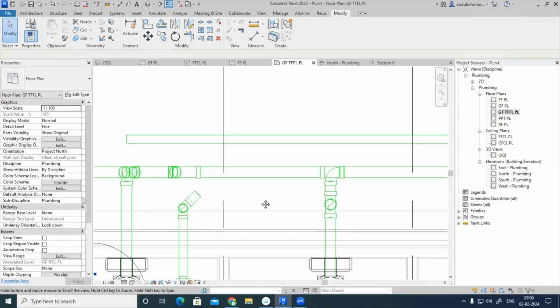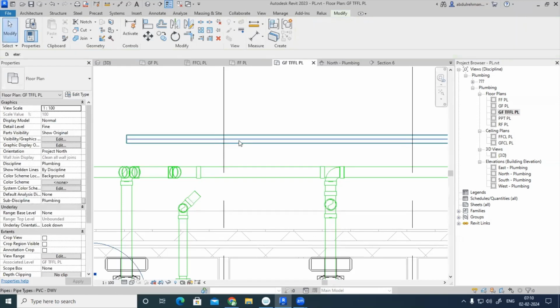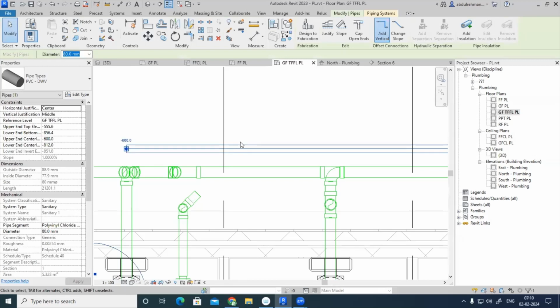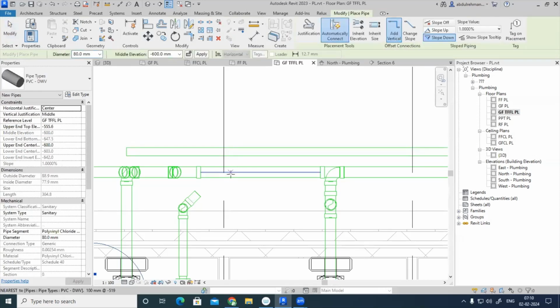I will do that. 1 second. So just create similar, and towards the pipe it is slope down, just the opposite of that is slope up only, because I have to align the pipe, then only can I perfectly connect it. So I'll be moving this pipe slightly to this side. Okay. And after that, just create similar. Anyhow, clashes will not come because both these pipes are located at a different level only. But clashes we can try in the collaboration session or in Navisworks also.